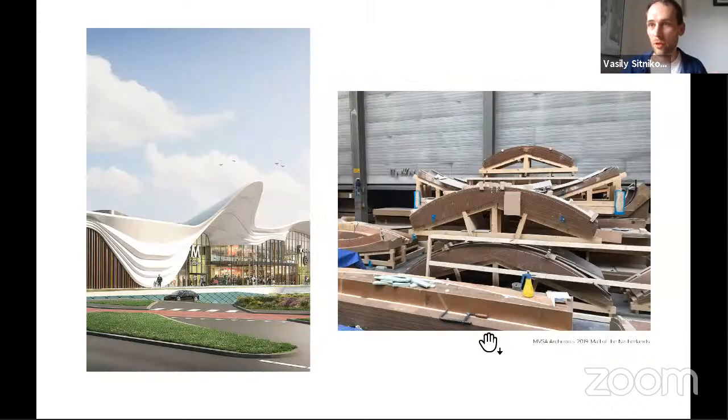However, for such a formwork, you cannot rely on styrofoam anymore. So for this project, a lot of MDF stock material was used and CNC milled in order to constitute a more robust formwork solution, which would comply with the very narrow tolerances required. Which is a bit of a problem for the budget because, volumetrically, MDF is way more expensive and carries way more environmental effect than the styrofoam, which is 98% air, right?